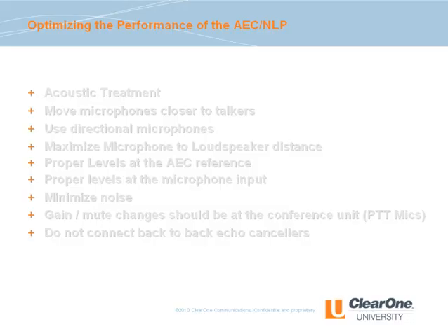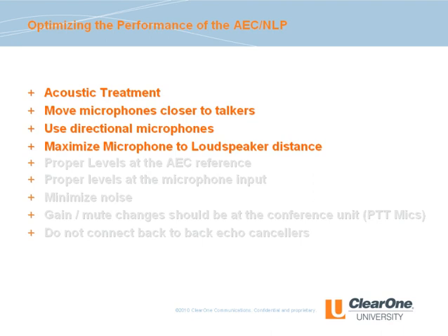So how can we improve the performance of the acoustic echo canceller? Acoustic treatment improves ERL. Move microphones closer to talkers. This improves ERL and the mic and talker to noise ratio. Use directional microphones to minimize acoustic echo and noise pickup. Maximize microphone to loudspeaker distance. Proper input levels ensure a good quality audio signal at the AEC reference. Proper levels at the microphone input. Minimize noise. Excessive noise can limit AEC performance.